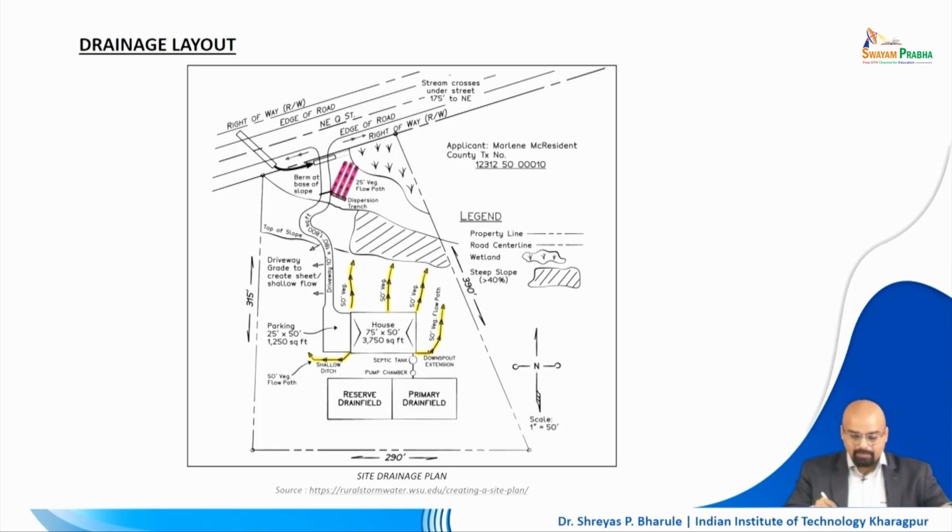That basically means that whenever there is drainage from this house, it will be drained off to this area, which is actually a storage spot called a dispersion trench. In this trench you collect all of the water in this area, which is a steep slope, and then you create a connection which takes all of your water to a wetland area for natural percolation.